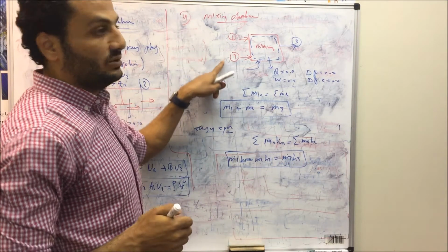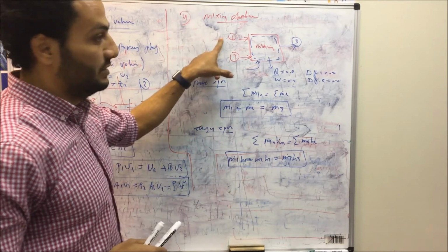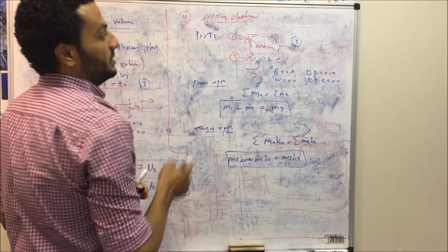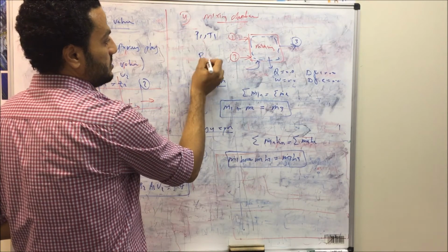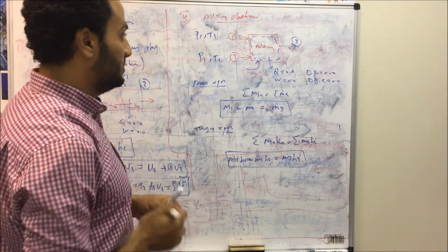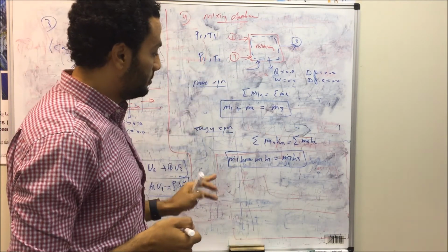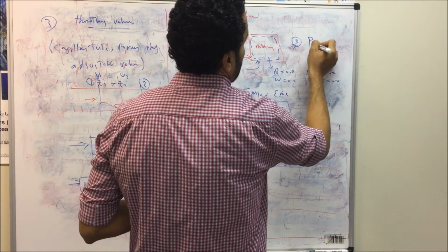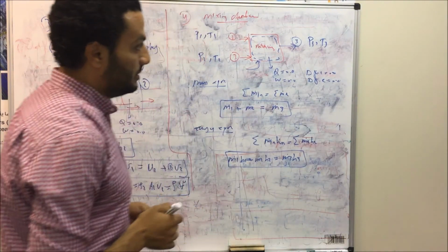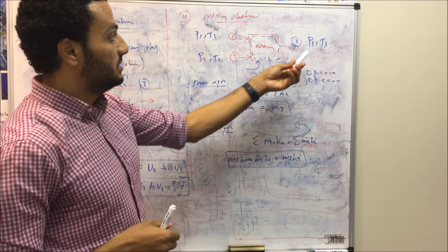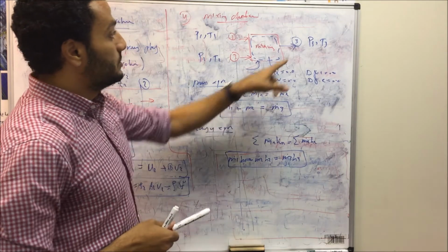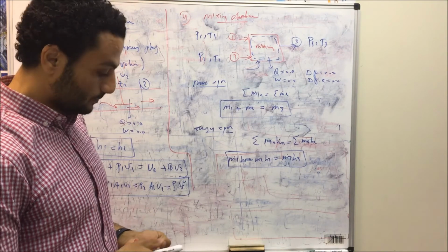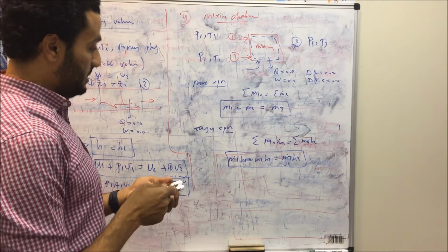So if you have steam and refrigerant at point 1, the condition will be given at point 1, P1, T1. In this case, we can just go to the table and get the enthalpy h1. Also at point 2, P2, T2, maybe steam or something for water. So at P2, T2, we can get h2. And also at point 3, we will have P3, T3, then we can calculate h3. Most probably in most of the cases, we will neglect the pressure drop. So usually P3 is the same as P1 and also the same as P2. This is the case if we have a mixing chamber.